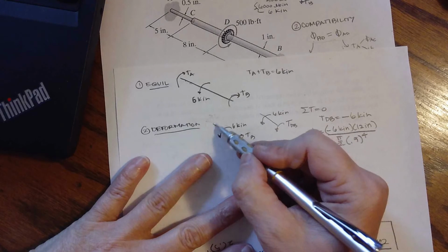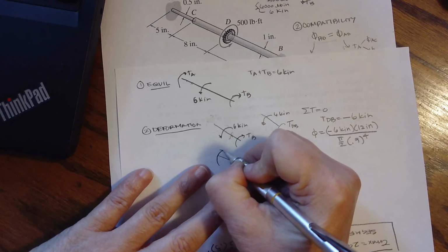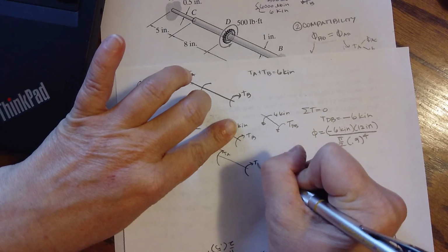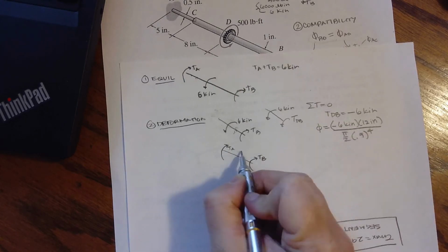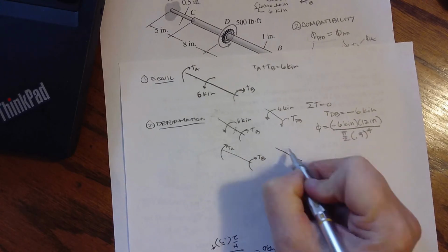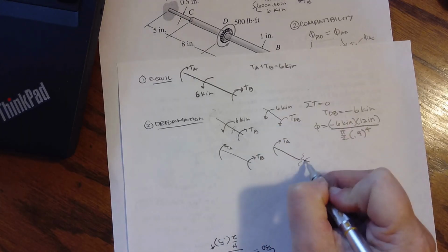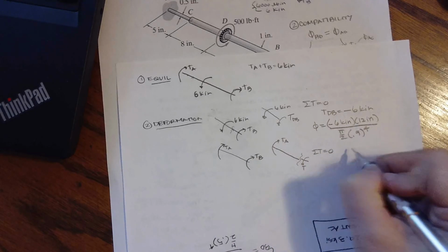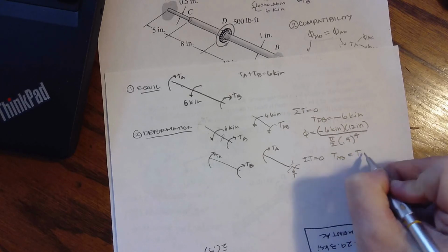Now I've got to put A back on. That was removing the redundant, so now we're going to put A back on. If I put A back on, I have the torque at A. I don't use that force anymore, and I have the torque at B. So now when I make a cut anywhere, here's my torque at A. I'm going to assume internal positive, and I sum my torques equals 0. The internal torque anywhere from A to B has to equal the torque at A, right? It's twisting it back. And what is phi from that?